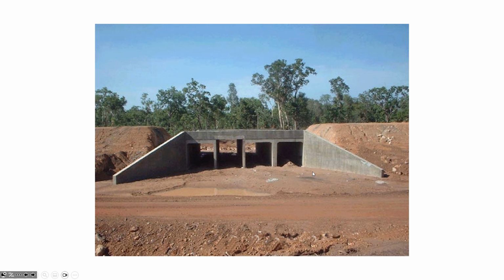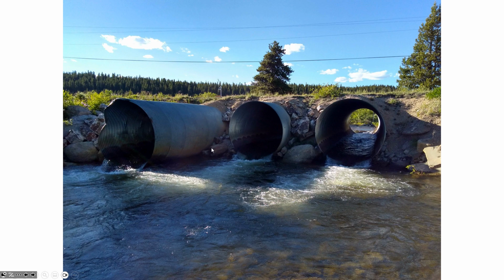And you can see that the purpose of these wing walls is to prevent water from scouring the soil that's supposed to be supporting the road that approaches the culvert, and also to guide the flow and try to reduce the amount of energy that's lost as it's approaching those barrels. Each one of these is called a barrel in the terminology of culverts. So this would be a 4-barrel culvert. This is a 3-barrel culvert.